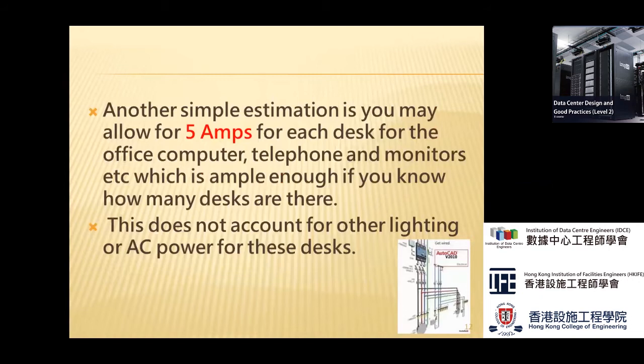Another simple estimation is that you may want to allow for 5 amps for each desk, for your computer desk. The computer is very small, normally 68 watts or less than 100 watts. Telephone and monitors, the monitors again are very small. No matter how many monitors you have, 5 amps should be enough because 5 amps can provide almost 1 kilowatt.